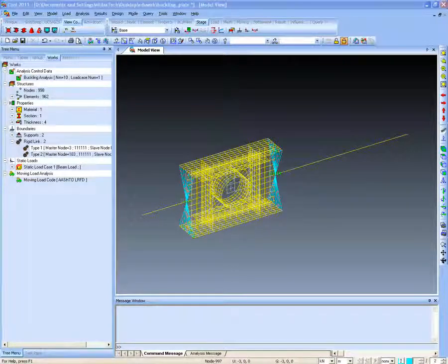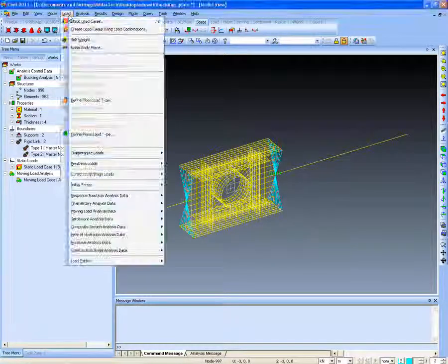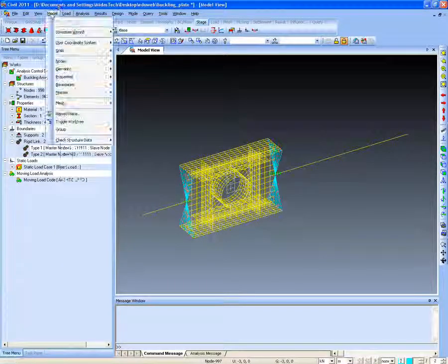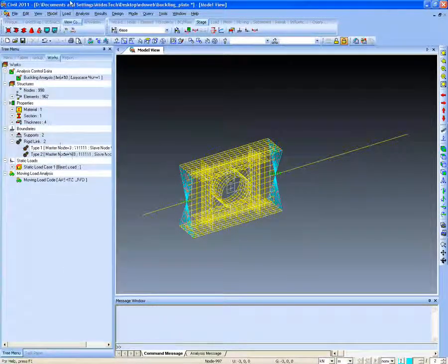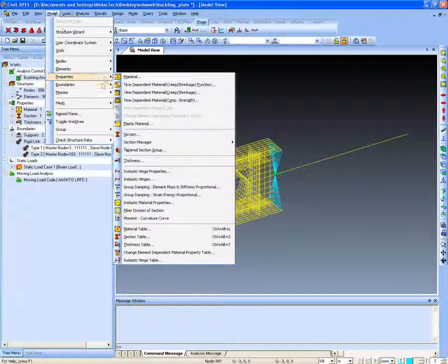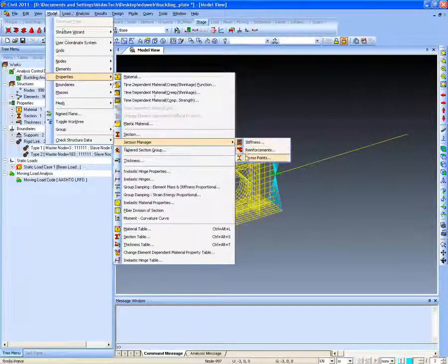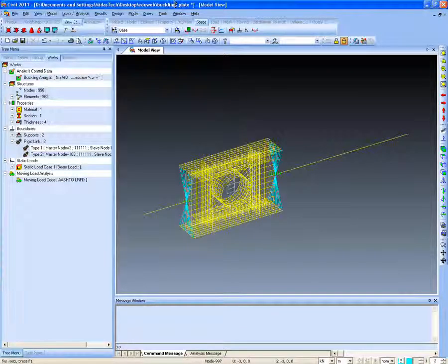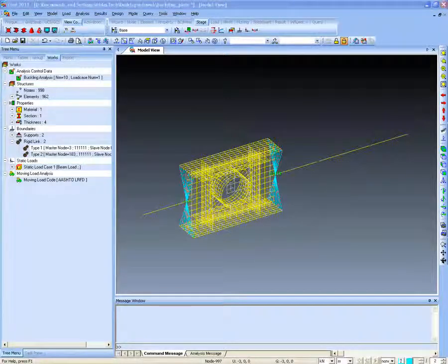Mr. Robert asked, how do we model lower E cross I on the inner supports by continuous composite girders? Yes sir, we can do that by applying the section stiffness scale factor. After applying the section stiffness scale factor, you can reduce the stiffness of the section, and if I'm correct, if you are talking about the cracked section, you can also simulate that characteristic. You can define the cracked section for the composite sections, and then in Midas Civil it can be analyzed as a cracked section.